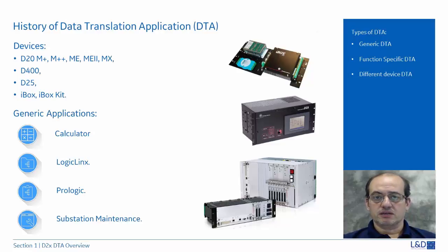Also, we've got the ProLogic and the Logic Links applications, which were developed over the years to allow customers to program using IEC standard programming languages. That allowed customers to put ladder logic functional diagrams inside the D20, which is a very powerful box that allows for execution of that logic.